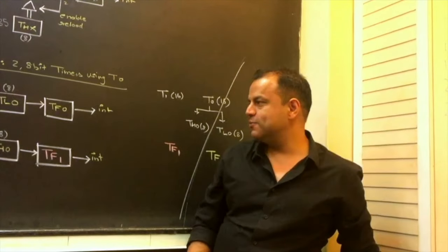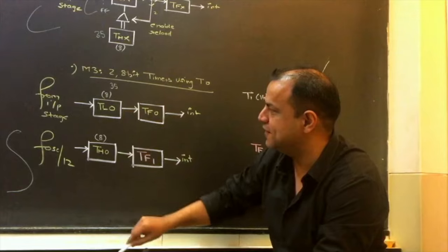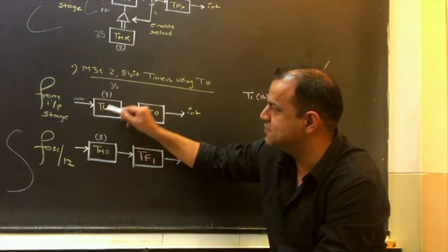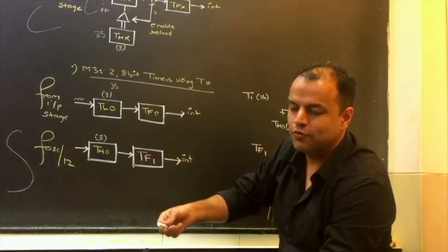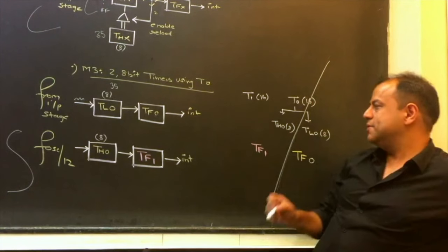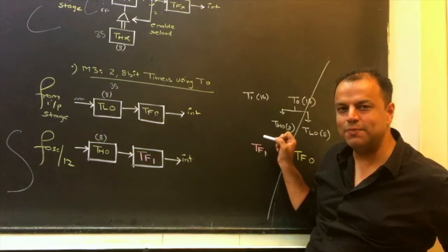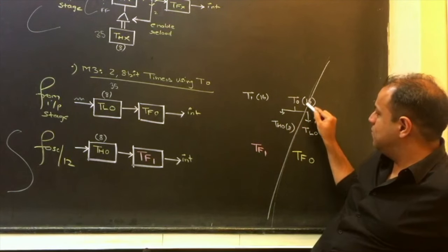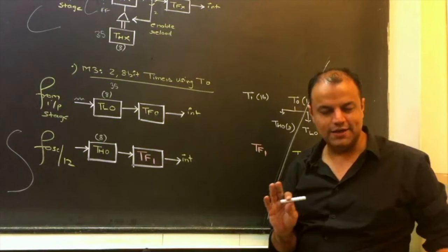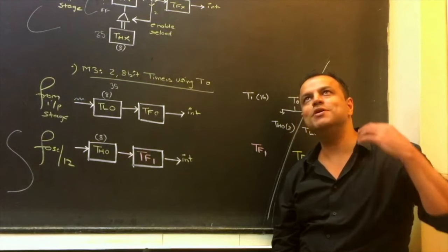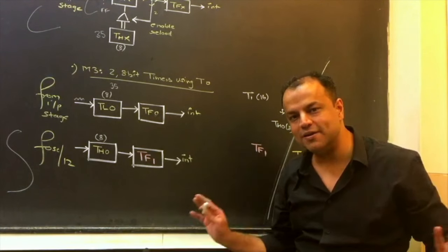Timer 0 lower byte wants to be an 8-bit timer, no problem. We give it a count, something like 35. On every clock pulse, the lower byte will increment. Eventually it will overflow. Till now, every time the lower byte would overflow, it would go and tell the higher byte please increment. Now they have become separate. When lower byte overflows, it is done. Now it wants to inform the processor, look, I have overflown, even I have become an independent timer now.